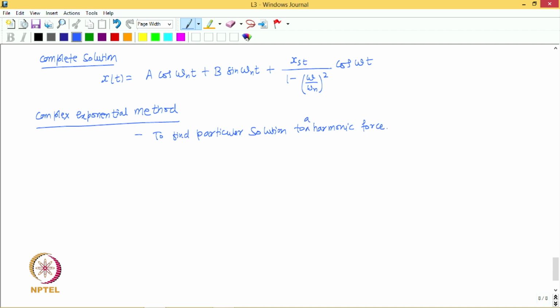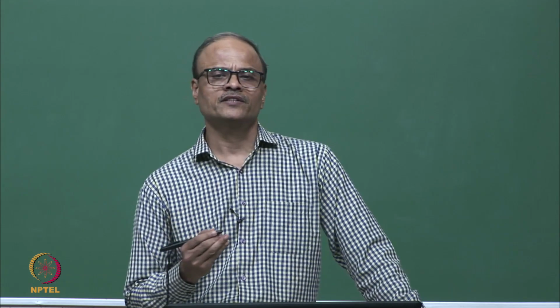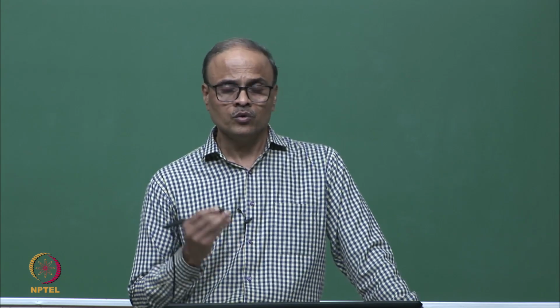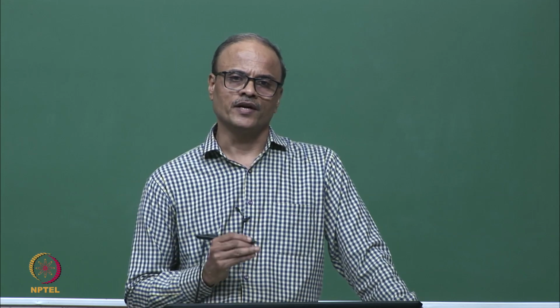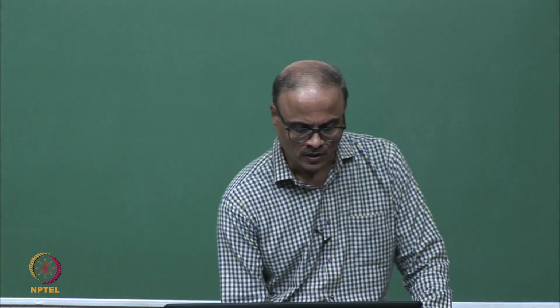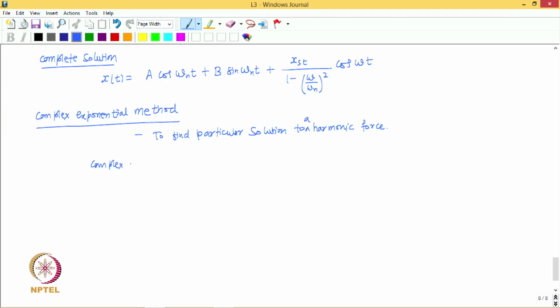So the idea of the method is that instead of finding the response to the actual force, which is F naught cos omega t, we find the response to a complex exponential force whose real part is the actual force F naught cos omega t. That is the idea. So therefore if we take the complex exponential force